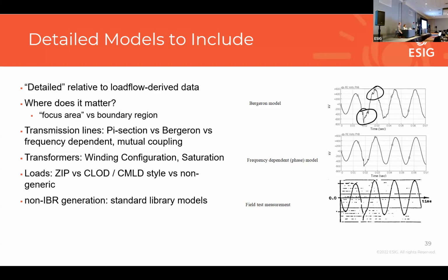So if you have your PSSE case or whatever, and you have a transformer with the R and the X, and you have the voltage levels, you can use that to create a transformer model inside of an EMT program.